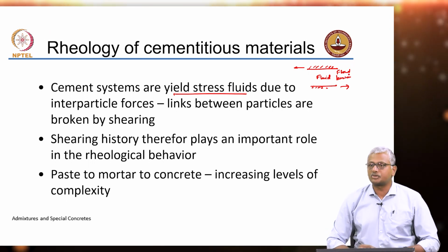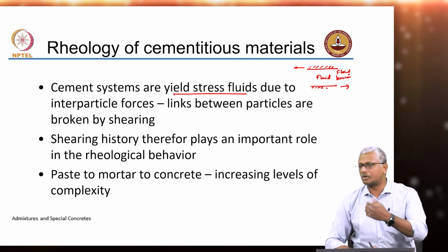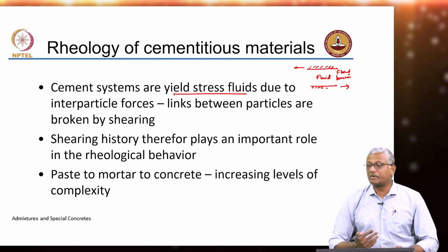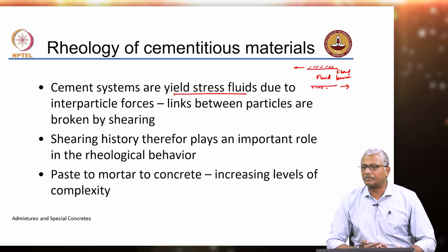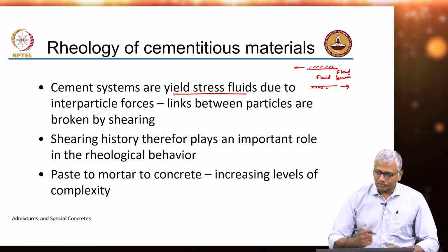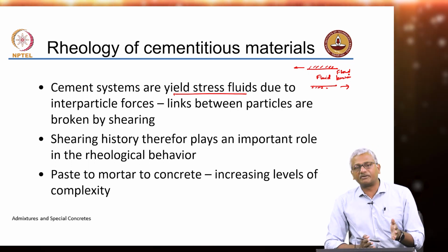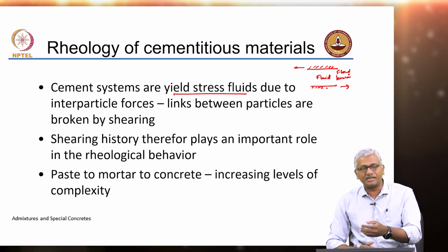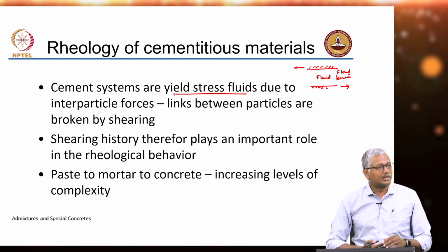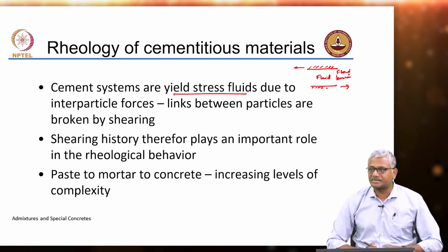The flow needs to be laminar, right? You've talked about this in your hydraulics lessons also, right? Flow has to be laminar. In turbulent flow, you can't really describe a viscosity. The material property of viscosity is defined in laminar flow. So, that's the textbook definition of viscosity. But we'll see here that the conditions don't always allow us to use this simple approach because of the sizes of the materials that are involved.